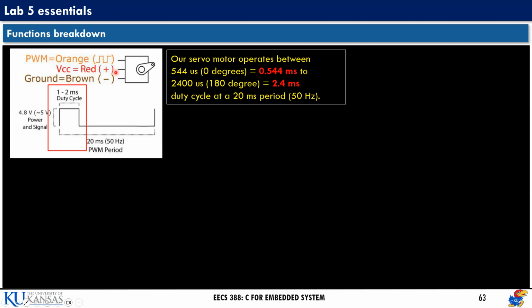That is the way the servo motor works with PWM, the pulse width modulation. The more we shrink or expand these pulses, the more we can rotate the fan of this motor. The other two pins are just VCC and ground. It's pretty straightforward. The red wire of this motor goes into VCC, that is 5 volt, and the brown wire goes to the ground connection.